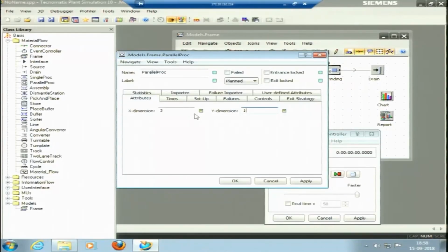Now, when there is waiting, when there is blocking, we can think of adding new machines, or taking a few machines off, and if there is a lot of waiting time, sometimes we can even think of doing some other processes, like I have said in case of the process layout. In a process layout, we have a specific set of machines in one section, another set of machines in another section. If we see the overall machine time, and in this specific section for 30% of the time there is a blockage, or waiting, we can give them some other job. Okay, some other job could be given.